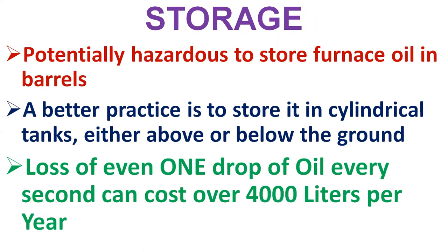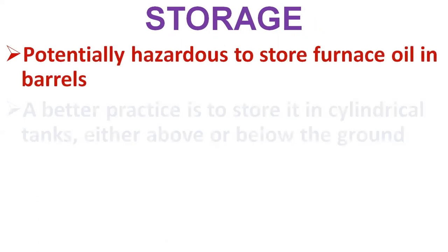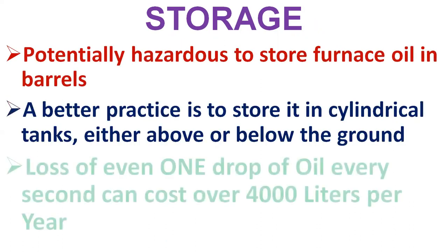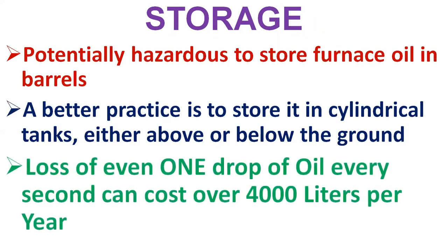Then there is the storage of fuel oil. It can be potentially hazardous to store furnace oil in barrels. A better practice is to store it in cylindrical tanks, either above or below the ground. Furnace oil that is delivered may contain dust, water, and other contaminants.